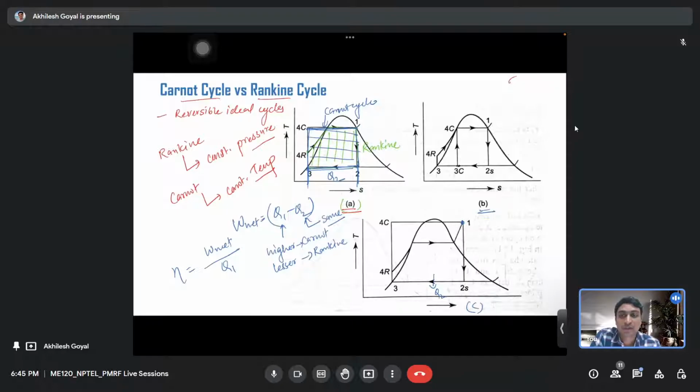So this shows that the Carnot cycle efficiency is the higher limit that can be achieved when the working fluid is working between two temperatures. One is the higher temperature, and the second temperature is the local sink temperature. The limiting value of that sink temperature is atmospheric temperature.